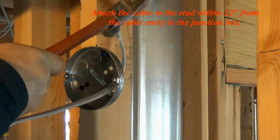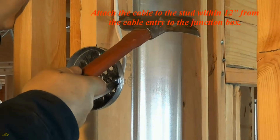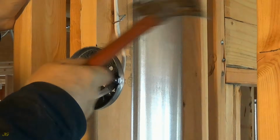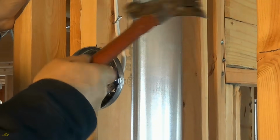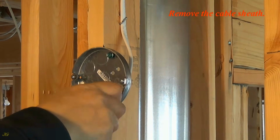Attach the cable to the stud within 12 inches from the cable entry to the junction box. Remove the cable sheath.